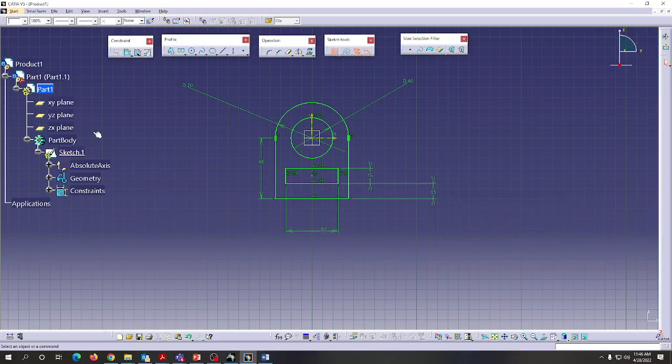Okay, why was it showing over constraint? Before, when we drew the rectangle, we took the center point rectangle, which has been aligned according to this dimension, since we chose the center point. So on this side and this side, from the vertical axis, it took equal distance. Again if I give this gap dimension as 10 mm, it shows over constraint, but I am able to give this distance length because I can locate my rectangle anywhere, either towards the upstream or towards the downstream. So when I chose this dimension, it was not showing over constraint, so I gave this dimension as 15. So that's all, we finished our drawing.